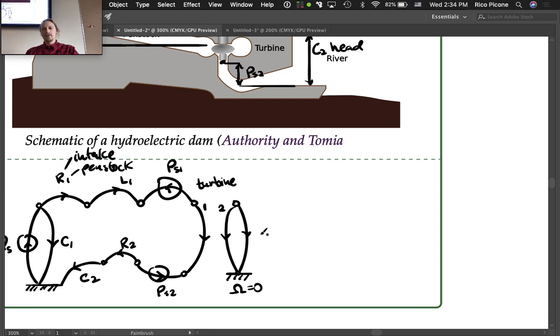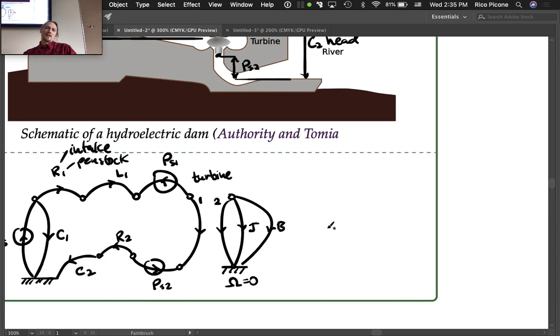That'll be a very significant effect typically. And another significant effect, probably with a big machine like this, is going to be the damping, the bearing damping, and also the internal generator bearings damping. So we'll lump that all into B.